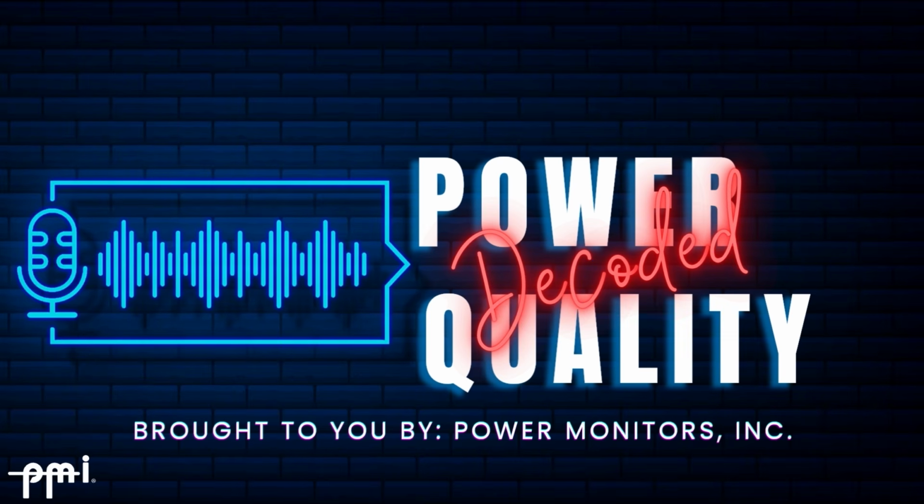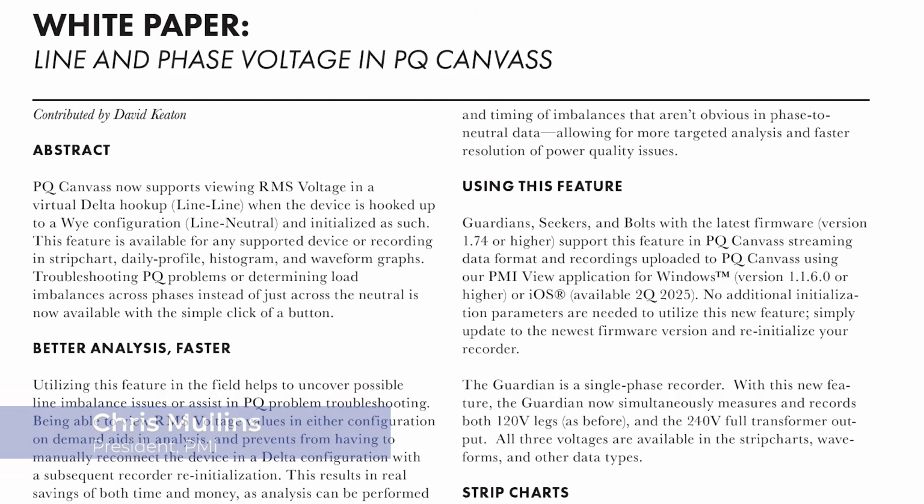Find us at powermonitors.com. Hello everyone, and welcome to today's white paper webinar. Today we are talking about a feature in PQ Canvas supported by the Bolt, the Seeker, and the Guardian to allow you to simultaneously look at line-to-line and line-to-neutral voltages. If you have a three-phase recorder connected as a Y, where you're measuring each voltage from phase to ground, or phase to neutral, you can now, in the recording, without any extra effort, also look at line-to-line voltages. So you can see the Y view and the delta view in the same recording.